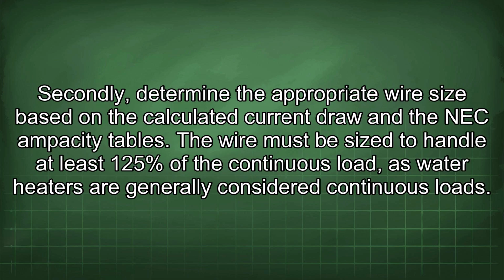Secondly, determine the appropriate wire size based on the calculated current draw on the NEC ampacity tables. The wire must be sized to handle at least 125% of the continuous load, as water heaters are generally considered continuous loads.